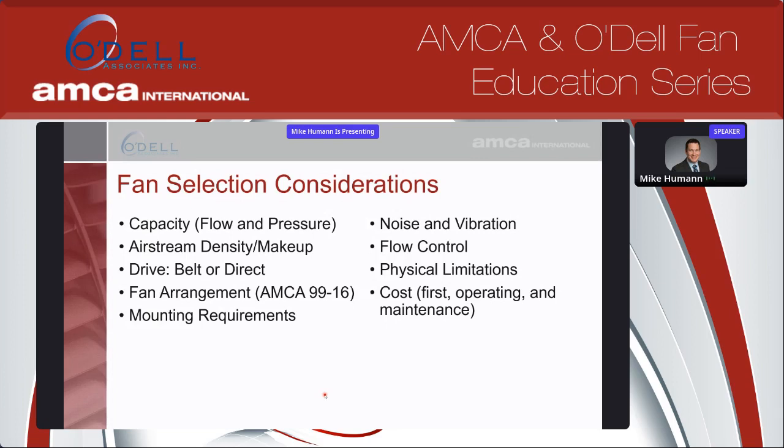And the last two really are physical limitations. That's more about the site and the envelope the fan's trying to fit in. And last is cost, and that's really critical because you definitely have that initial capital cost. And an initial capital cost on one fan versus the next can be drastically different depending on some of the other requirements. Are you looking for the most efficient fan? That's typically going to be more expensive than a fan that's not as efficient.